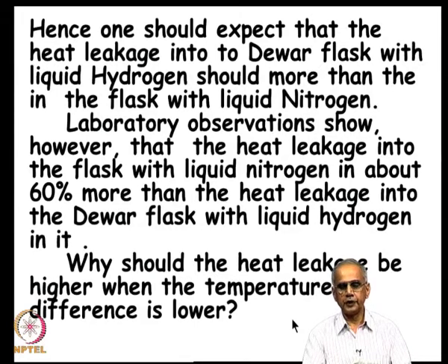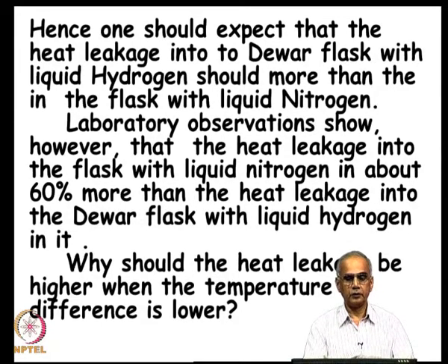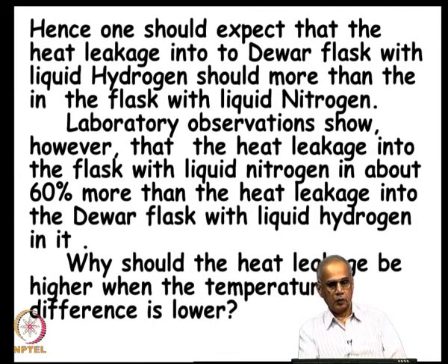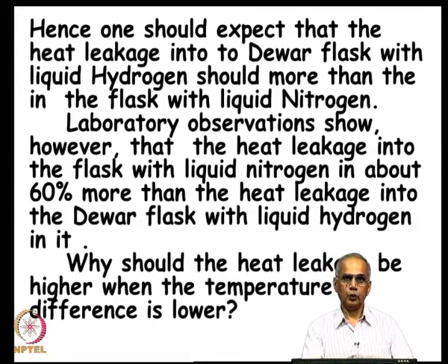So, laboratory observations show that heat leakage into the flask with liquid nitrogen, which has a lower temperature difference, is about 60% more than the heat leakage into the Dewar flask which contains liquid hydrogen. So, the question is, why should heat leakage be higher when the temperature difference is lower? So, this is the issue we want to address and understand from radiation heat transfer.